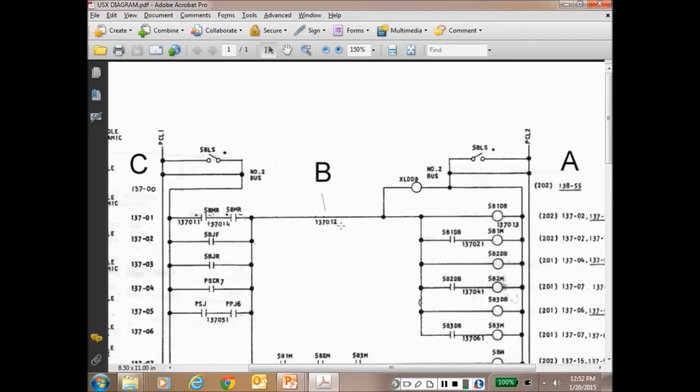And it was real neat because it was a continuous strip furnace, mill, and they could stop the feeding in, and they could stop the takeoff in, and never stop the center. They couldn't stop the center because it was running through a furnace. They had to preheat it, so they had to get it up to the right temperature so the zinc would adhere to the metal. If you stopped it inside the furnace, that's what would happen to the strip. It melted in two.